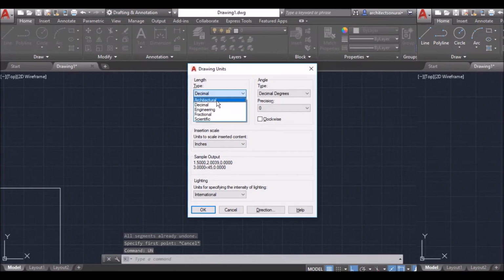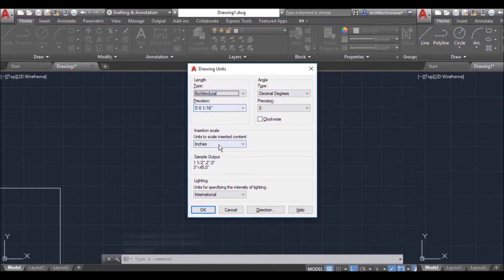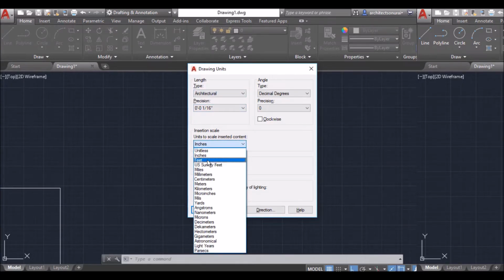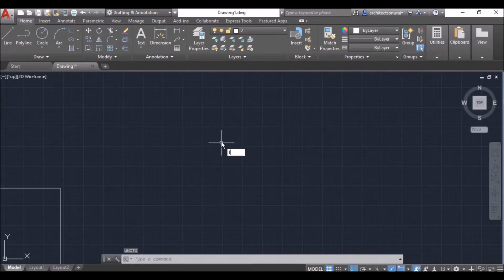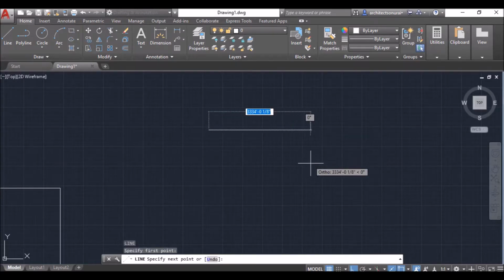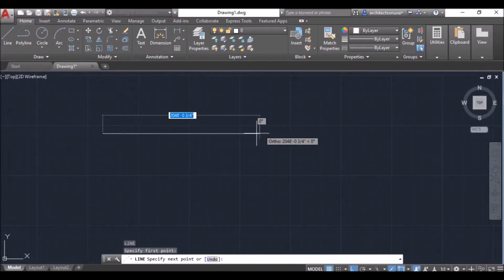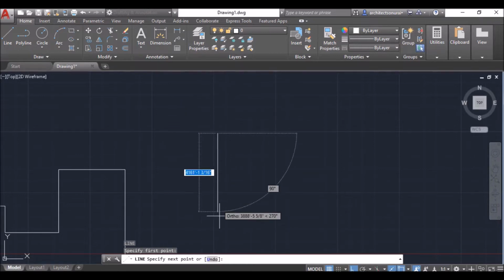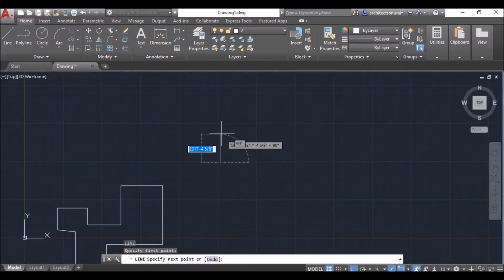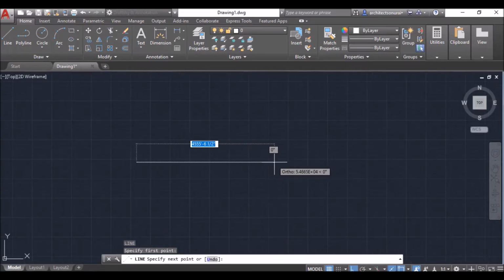If you want to work in feet, I select feet here to mention this. After that you can start. If I am drawing a line, now it is showing in feet. Suppose you want to make drawings like a residence; now ortho mode is on, and it is showing 90 degrees. Suppose I am going this way and want to draw a room 20 feet in size.